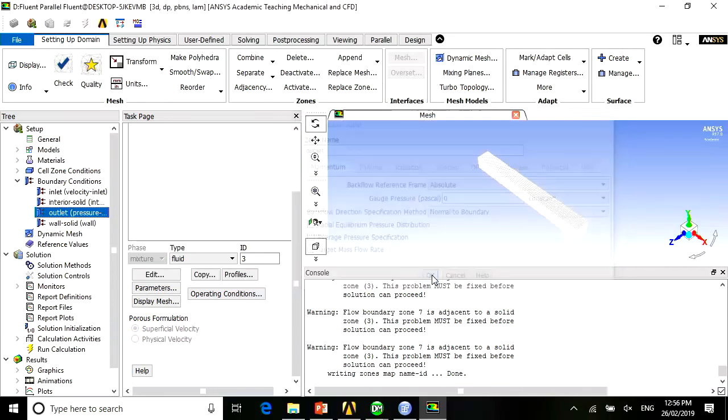You say, okay. Now, you notice that if you look at CFX itself, the solver control is less complicated. You have advection to be high resolution and two numeric steps. Now, there is a fundamental difference between CFX and Fluent. Now, I'm getting very technical now. In terms of the solver for CFX, it uses a so-called direct solver. What it means by direct solver is that the velocities and the pressure are solved simultaneously.